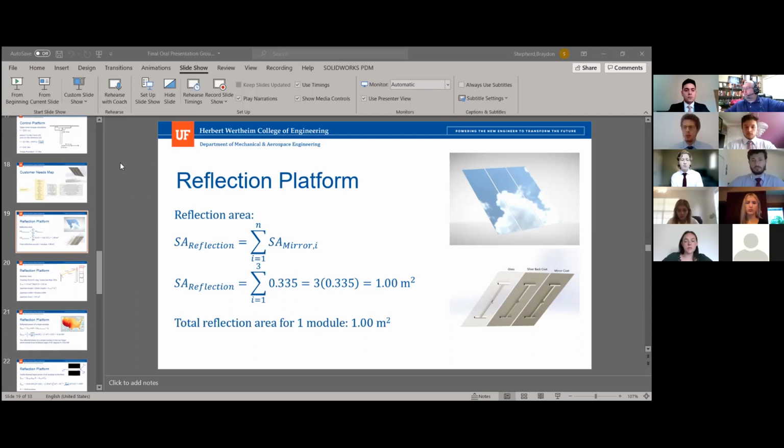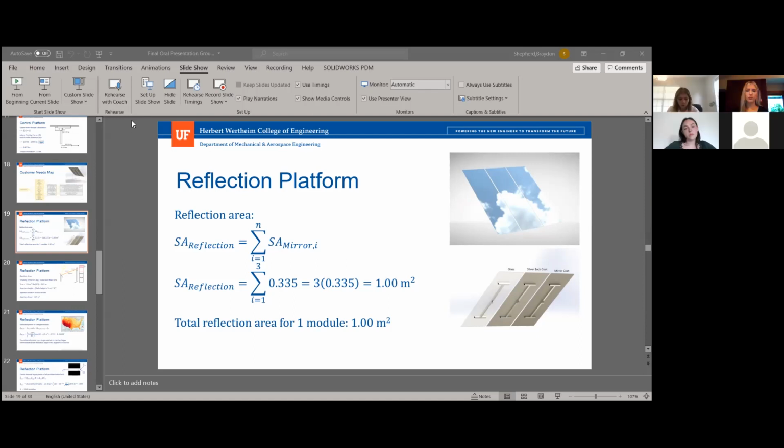I wouldn't be as concerned about cleaning the glass, although potentially things scratching the glass are going to impact the efficiency of your system. But I wouldn't expect any cleaning to happen on the back of these, especially if it's being serviced by some sort of system that's mounted on a passing truck. But I guess I would have a concern about dust blowing and abrading the reflective coating on the backside of these mirrors. If that's exposed, that's a concern.